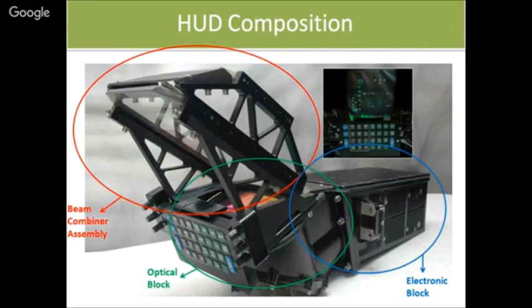The job of the electronics block, if I tell it in the simplest of terms, is to get information from the mission computer of the aircraft and convert it into a form which is suitable for the CRT which is fitted at the end of the electronics block. In simplest terms, you have certain signals, you have certain image information. Naturally, image information in analog form is nothing but XYZ. Here we have differential signals, X plus X minus, Y plus Y minus, Z plus Z minus. I have to convert them as per the requirement of the CRT. I have to display it on a CRT.